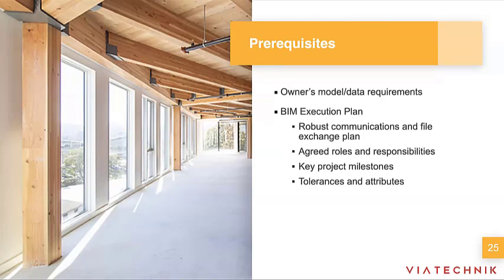And typically, for prefab projects such as mass timber projects, we're looking for an LOD 400, which is a fabrication level detail. However, depending on the project and the client, that might vary in some cases. And then also knowing the project and client goals will allow us to determine and also track and measure the success in this project.